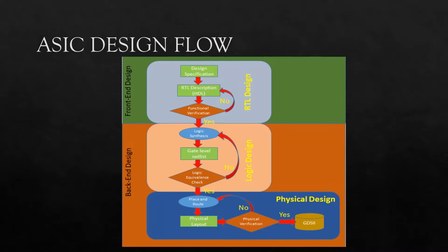If you take any protocol, like APB, AXI, or anything, before implementing it in your code, you need to go through some set of rules and features, as an RTL design engineer as well as a verification engineer. If you are a verification engineer, you need to point out test cases: what are the things I need to test, which features I need to test. For each and every feature you have specific test cases. These can be decided through the design specification. This is nothing but a set of rules.